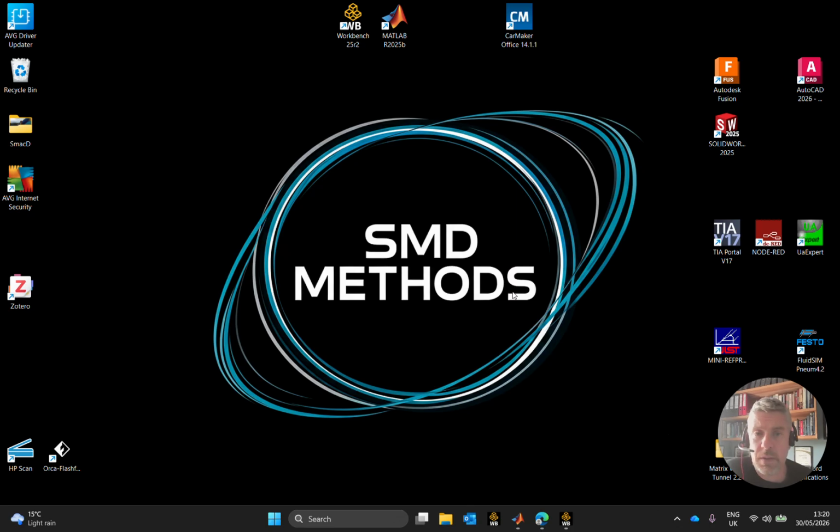This is the third in the series looking at the front wing of a Formula Student Car application. The last video finished off with altering parameters that were developed during the first video, which was the establishment of the flow field geometry within ANSYS Design Modeler. So in this video I'm going to proceed on and we're going to mesh that flow domain. Then from that subsequently we'll take it on a grid convergence index study for mesh independence, and then into further assessments of other elements for that front wing.